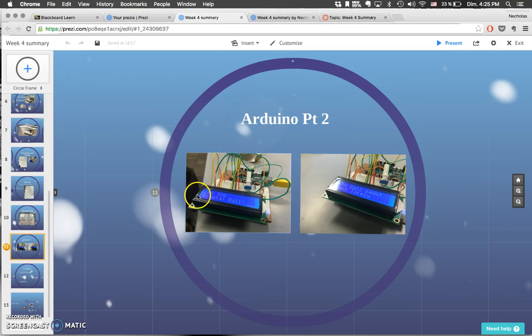The code for this one was pretty hefty, but everything needed to be there. One particular thing I found interesting was on this line, you have to actually tell the LCD panel how much it can display. So it can display 16 characters on the first line, 16 characters on the second line, and so 32 characters in all. And you actually have to type out ask on one line, and then tell it to move the cursor to the second line to say the crystal ball. So you end up with 2 lines of code.